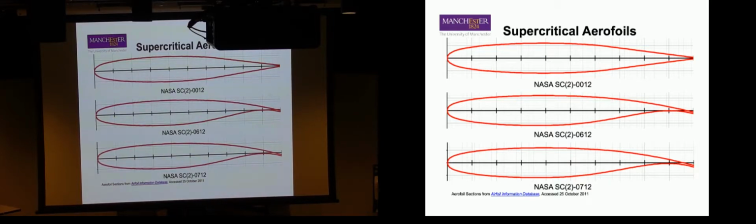If we did it infinitesimally small, we would get what? An infinitesimal change in speed and an infinitesimal change in pressure is what is called what? You're listening to it right now. It's called a sound wave. We have a finite step change in pressure, we get a shock. The bigger that step change, the stronger that shock is.